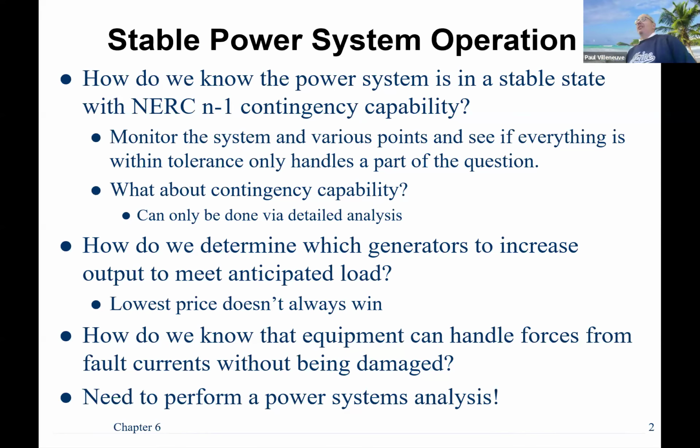So the load models, and we talked a little bit about this early in the semester, the load model is something that we have to consider. So we talked about constant impedance or constant power. And we typically like to have constant power if we can, because again, the customers are paying for the power that they're using. So if it acts like a constant impedance, then as the voltage drops, the load decreases. And as a result, we end up not making as much money.